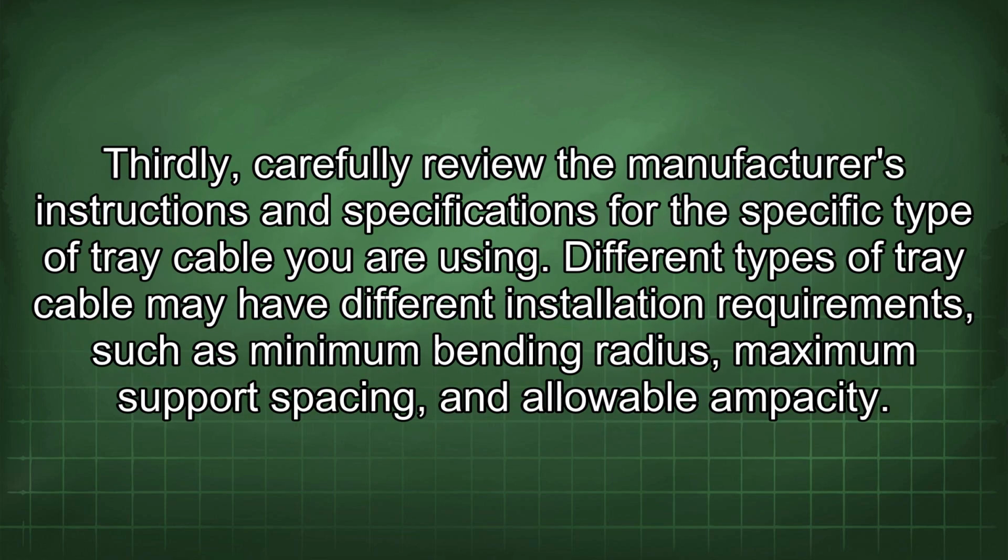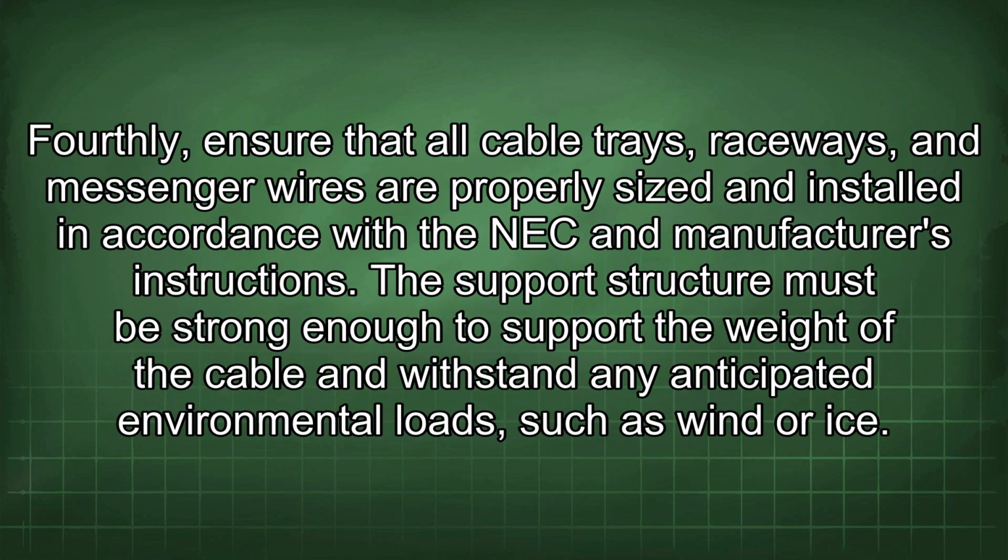Thirdly, carefully review the manufacturer's instructions and specifications for the specific type of tray cable you are using. Different types of tray cable may have different installation requirements, such as minimum bending radius, maximum support spacing, and allowable ampacity.